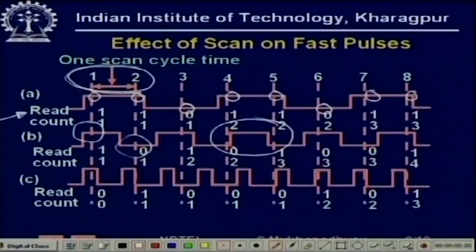So, you see that when the program scanned this pulse, the value was 0, and when the program scanned it next, the value was again 0, and so the program assumed that it remained 0. That it went up to 1 in between and came down, the program will be unaware of that, and therefore there will perhaps be a small delay in the computation of the speed.